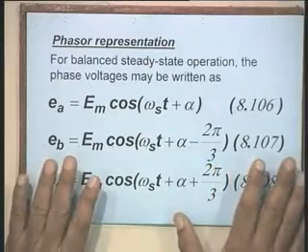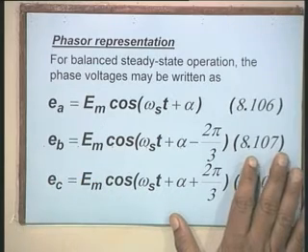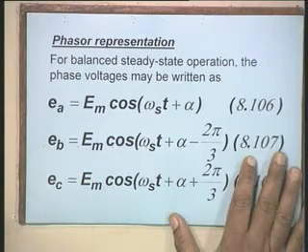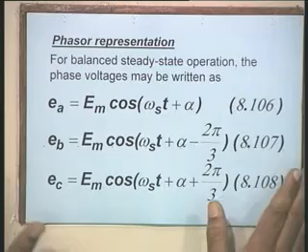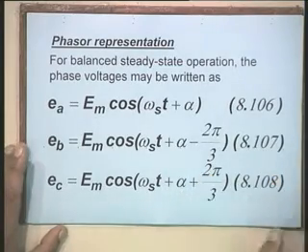ED, EQ, ID, IQ, they are scalars. But because there exist trigonometrical relationships between certain phasors and the D and Q axis components, we can represent these quantities in the phasor diagram.